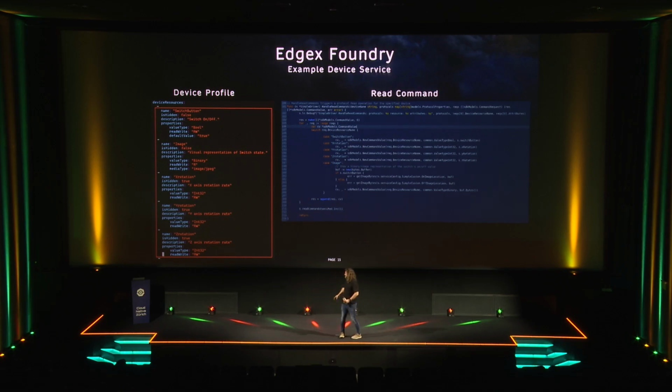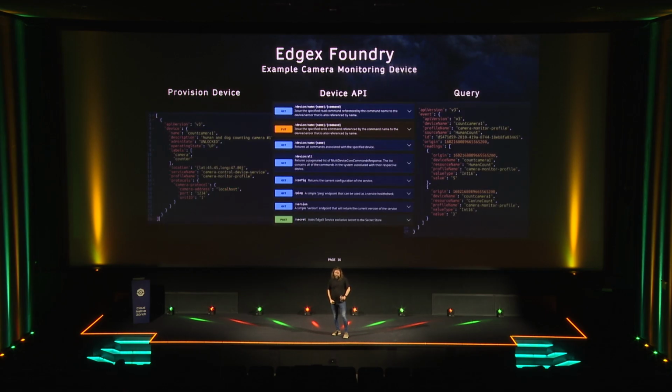So this is just an example of how to handle a read command for that device, and that means once you create that device service and bring it up on an EdgeX environment, it can register itself with EdgeX just through a simple API. The applications that are there can understand, by querying EdgeX from your device profile, what type of data your device reports, and start querying that data, but also interacting and commanding that device automatically without having to change or have specific knowledge of that device.